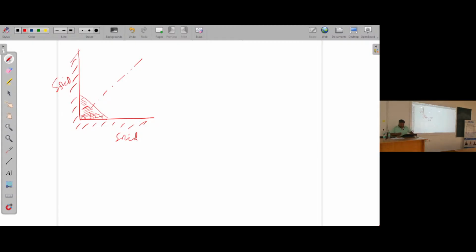So basically, let's say this is an area of delta A. This is also delta A. If this is delta A, and you want to fill this up, this would be something like delta A sine 45 degrees. This is the area projection there. And what we are looking at is this guy, this is liquid. So this has a surface tension of sigma LV.